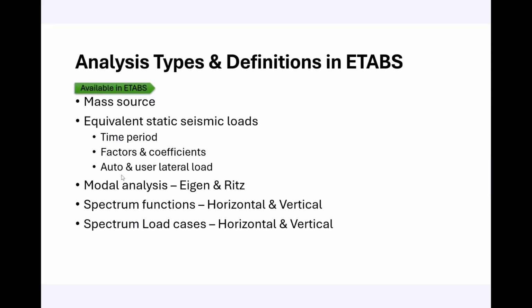To apply the user lateral load, you will have to have the diaphragm assignments on the floors. So this will expose the diaphragms in the building, and you can specify the load directly in the FX, FY, and MZ for any twisting moment.